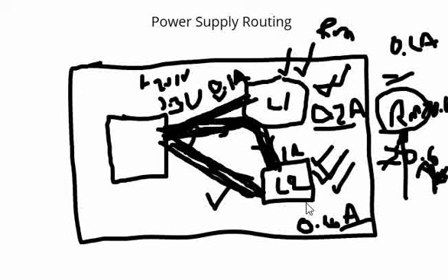Meanwhile, having a thicker copper trace to another load of higher current is feasible. So very simple scenarios, right? And as we mentioned, the routing also has to be decided depending on the kind of voltage that needs to be supplied to these loads. Very important tips while routing. Please post your suggestions, comments.